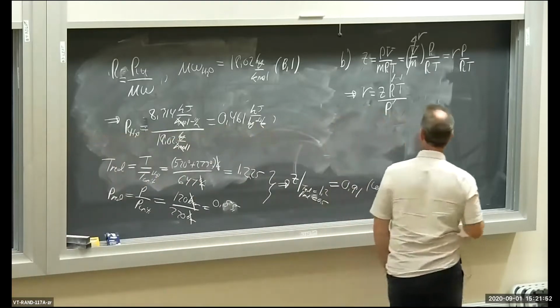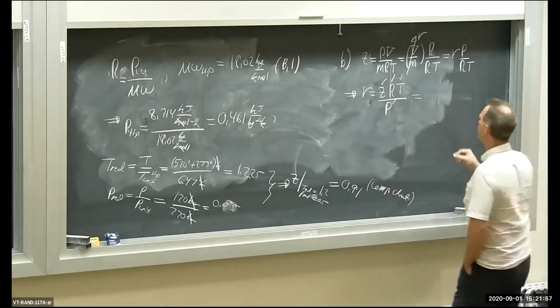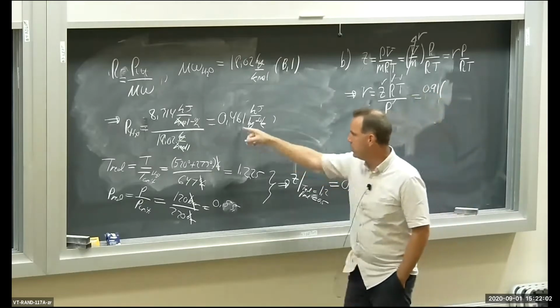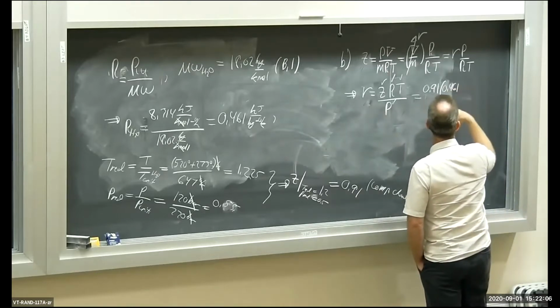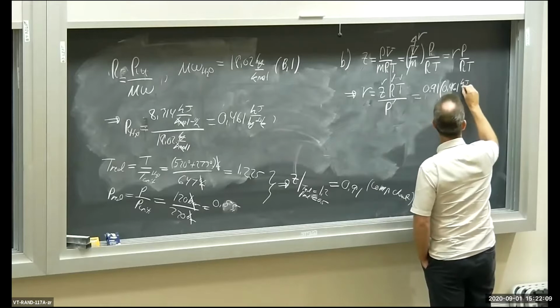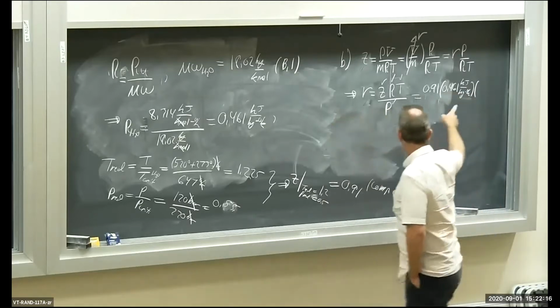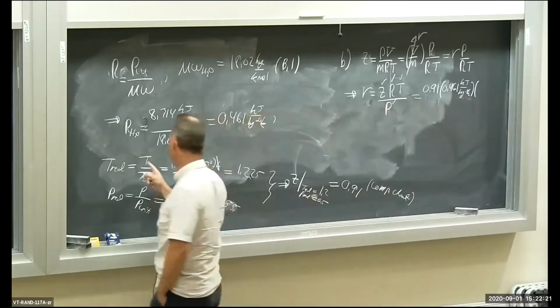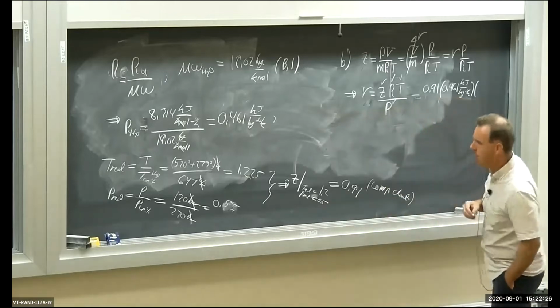All right? Okay, let's finish the calculation here. Let's calculate the specific volume for our H2O. We now have the compressibility factor is 0.91. So 0.91, gas constant 0.461, and that has units of kilojoule per kilogram degree Kelvin. The temperature, Kelvin. Kelvin is the temperature unit in the gas constant, so we have to give temperature in Kelvin, so that's 520 plus 273.